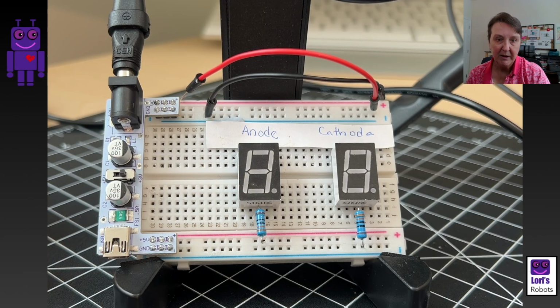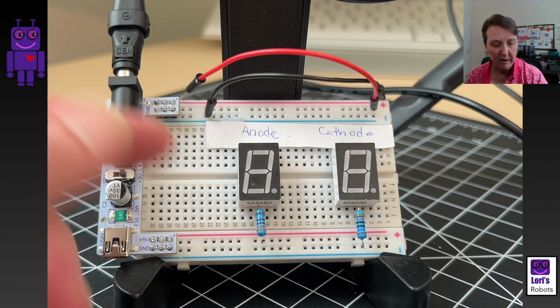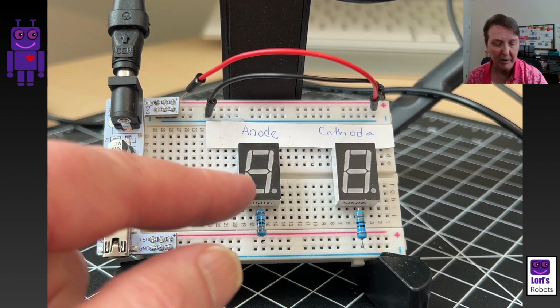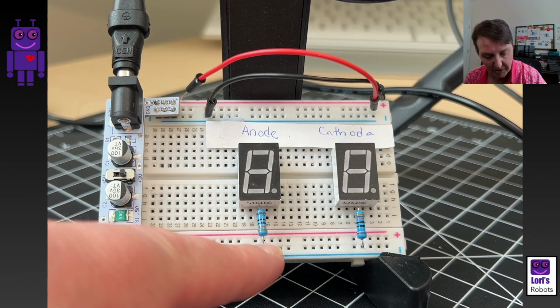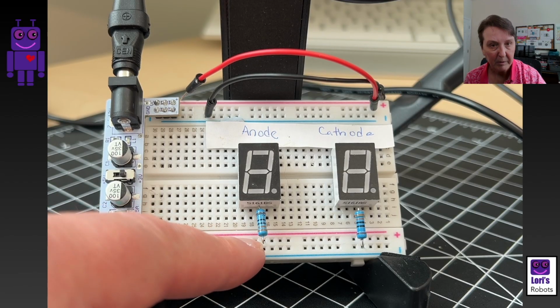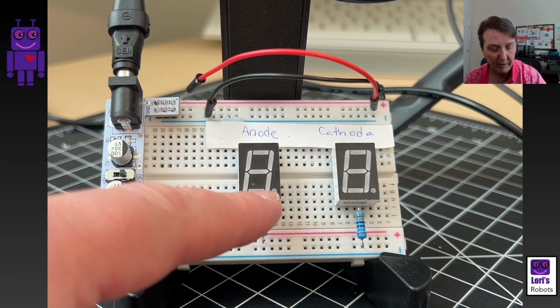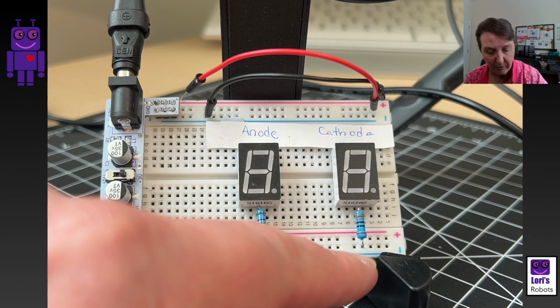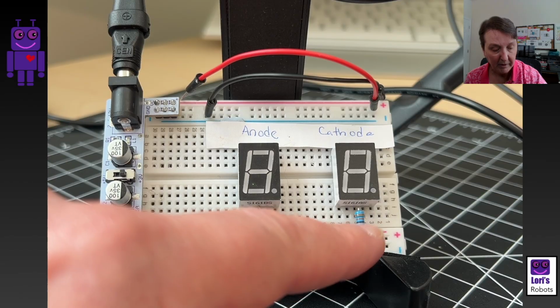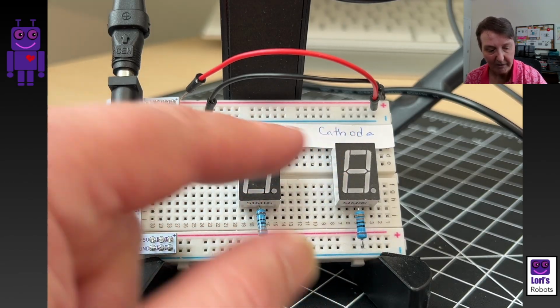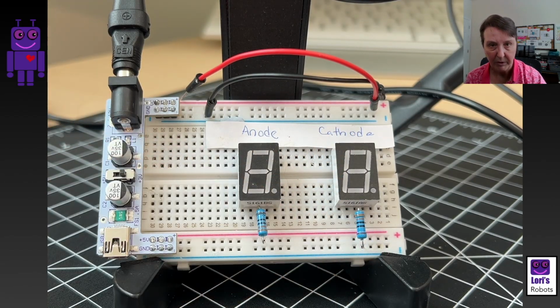And it turned out in my kits I had both kinds. I had mostly cathodes, but I did have some anode as well. And here you can kind of see, it may not show up quite as well, but the common anode I have connected to the power on the common pin. And for the cathode, I have it connected to ground, that common pin. You'll notice I didn't have to have it connected on both sides. Just pick one of the common pins or the other, whatever's convenient.